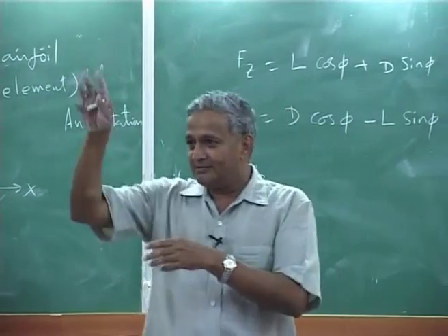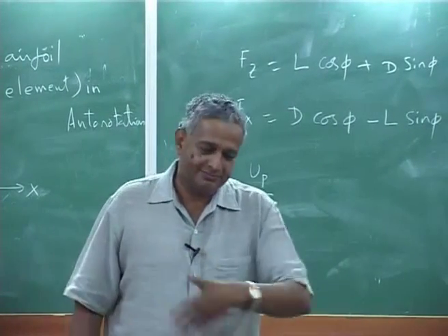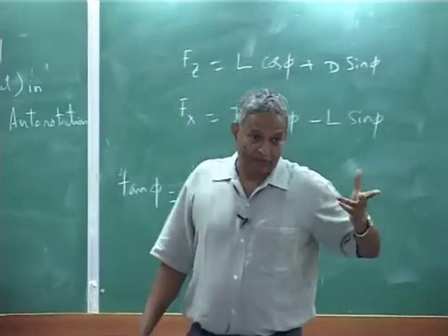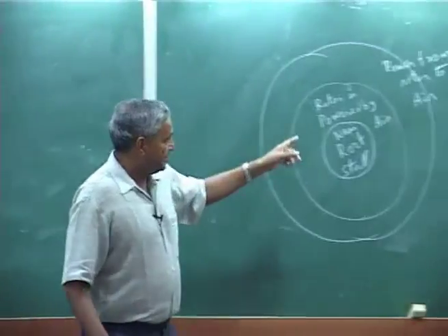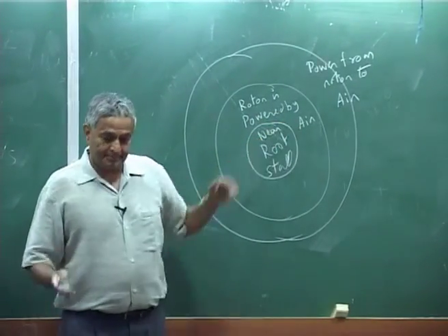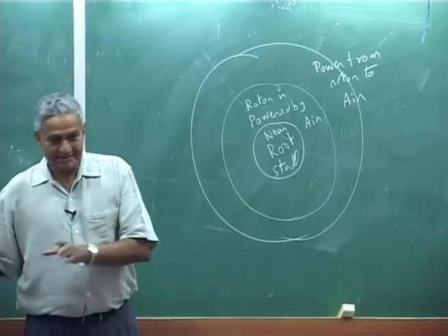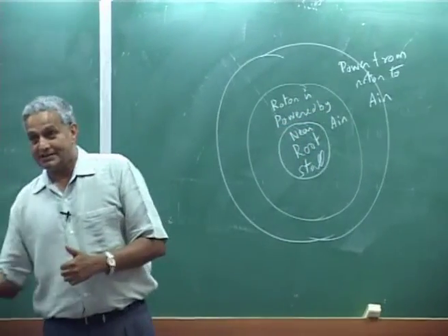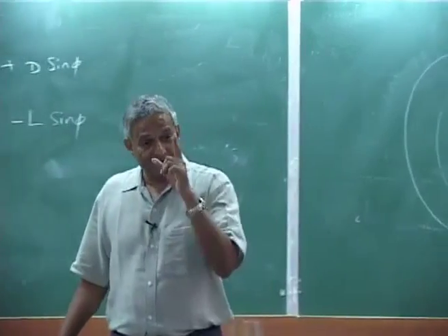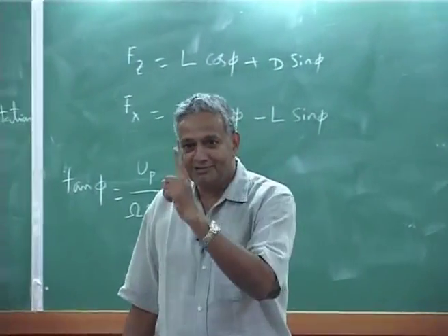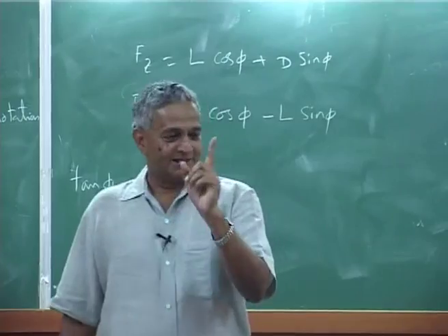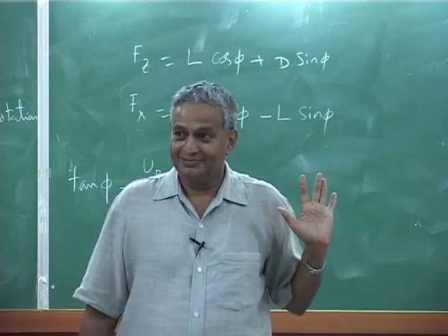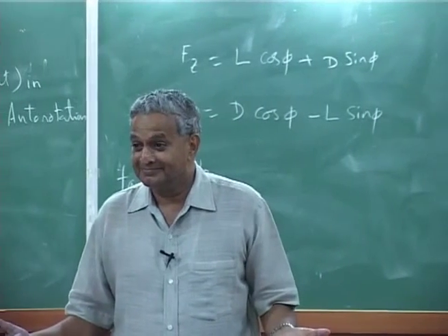Now, you see why they neglect that. I gave you 0.15 in the homework, root cut out, throw it. This is the region. Now, the integrated value of the region where the air is pulling, the rotor is actually getting that. Net value is 0. That is auto rotation. That means, the rotor blade will continue to rotate at the same RPM.